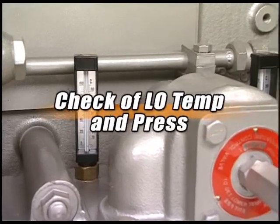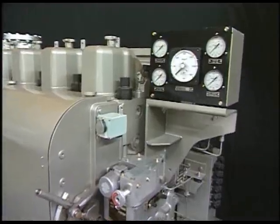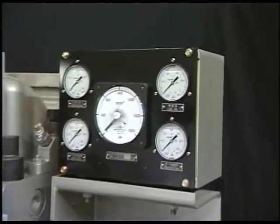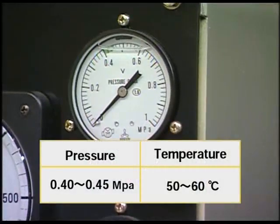During the engine operation, check that the lube oil temperature and pressure are within the specified value that you are watching in the video. If they are out of specified value, try to find the cause and take appropriate measures. Here, I will explain the procedure for operating the adjusting valve of the lube oil pressure and thermostatic valve on the engine side.